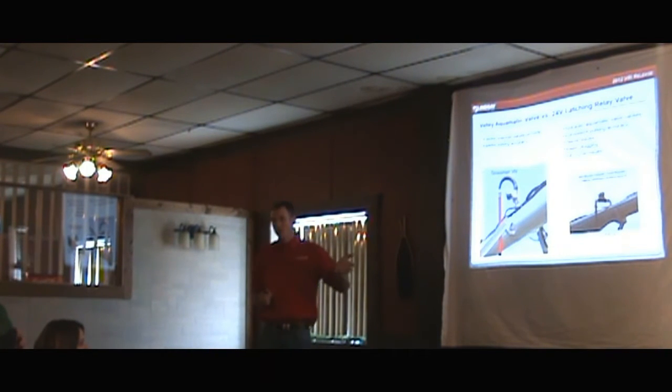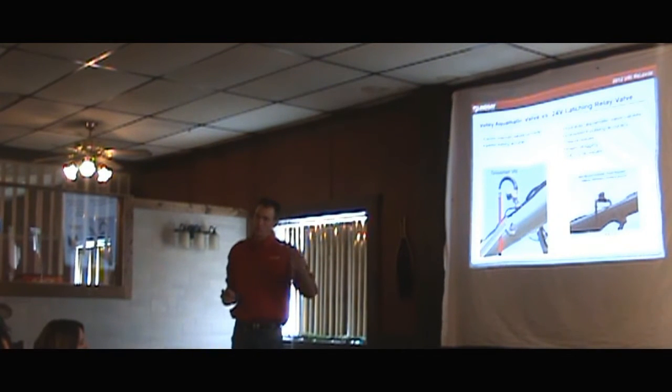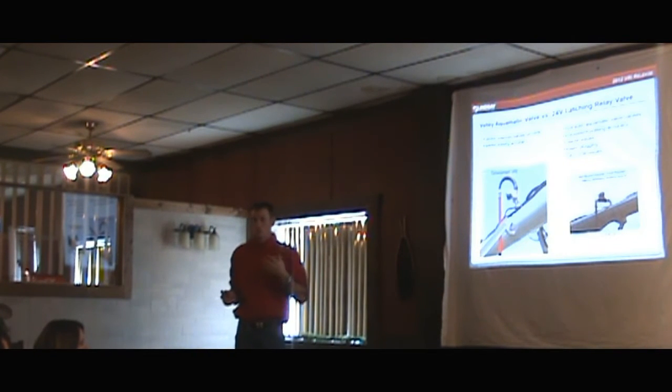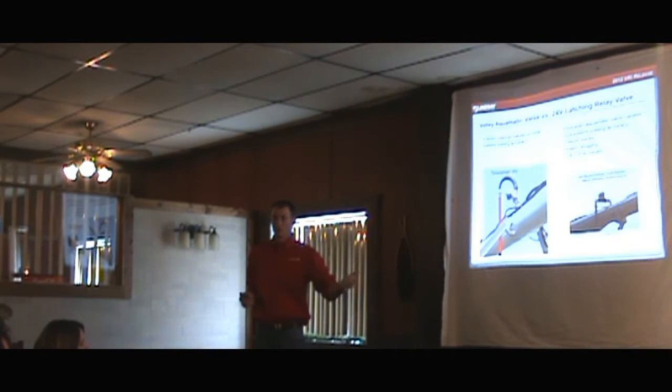Being a plastic valve, you run into corrosion issues with galvanized goosenecks or metallic properties, like the old brass valve, but the plastic is better with some of that. It doesn't gum up in there as bad. We've had a lot better success with the tougher waters with this valve. Did I answer your question?